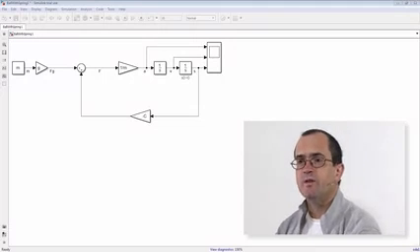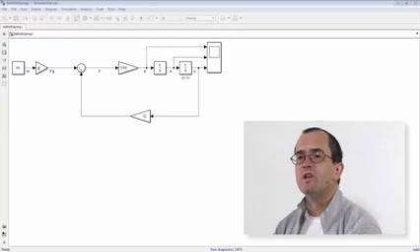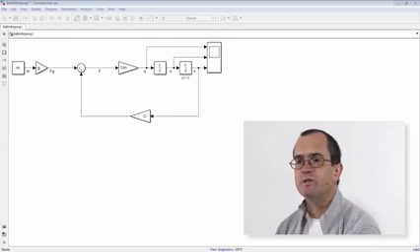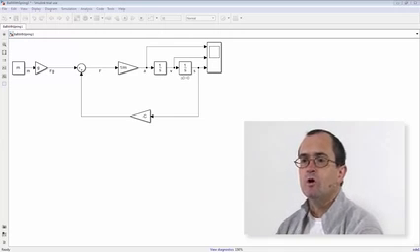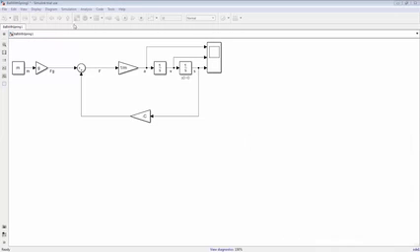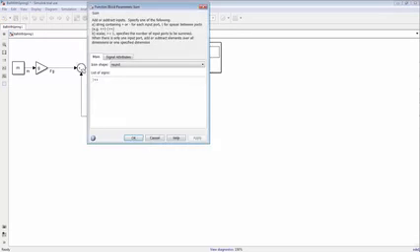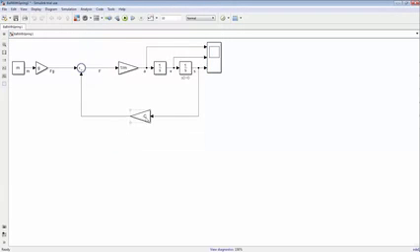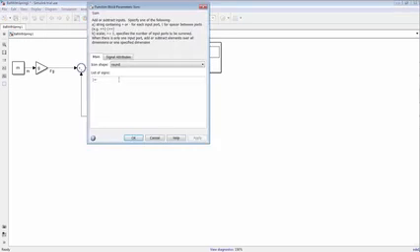So, we've got this model. While the model is mathematically correct, the minus sign usually is not entered in the gain block representing the spring constant. The actual place experienced Simulink users are looking for the sign information is the sum block, as you see here. Change it here, at the minus port. By double-clicking on the sum block, you see the representation of the signs in this block's input ports.